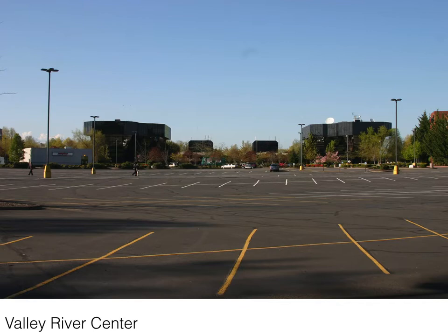The parking spaces themselves are usually about 8 feet by 18 feet, and the space between them when you're doing perpendicular parking usually has to be about 22 feet. So I always just sort of say when I'm laying out a parking lot that if you're doing a double-loaded circulation, from a car stall, the aisle between them, and then the next car stall, that's about a 60-foot width you have to allow for there.